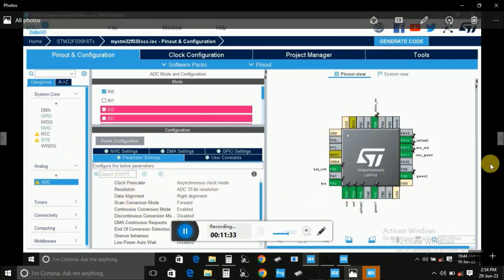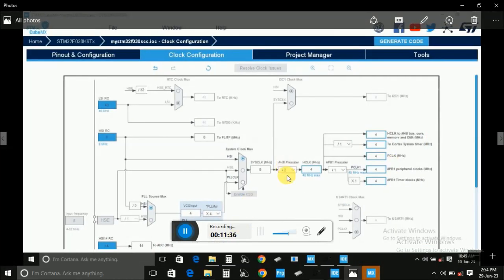naming and configurations, right? The timing here, I had an issue with the timing of the IC, the clock configuration. It was only accepting around 4 megahertz. Actually, it wanted 3.6, if I'm sure. It didn't want any other higher clock speed. I don't know where I was going wrong. Maybe someone can give me feedback on where I was going wrong.